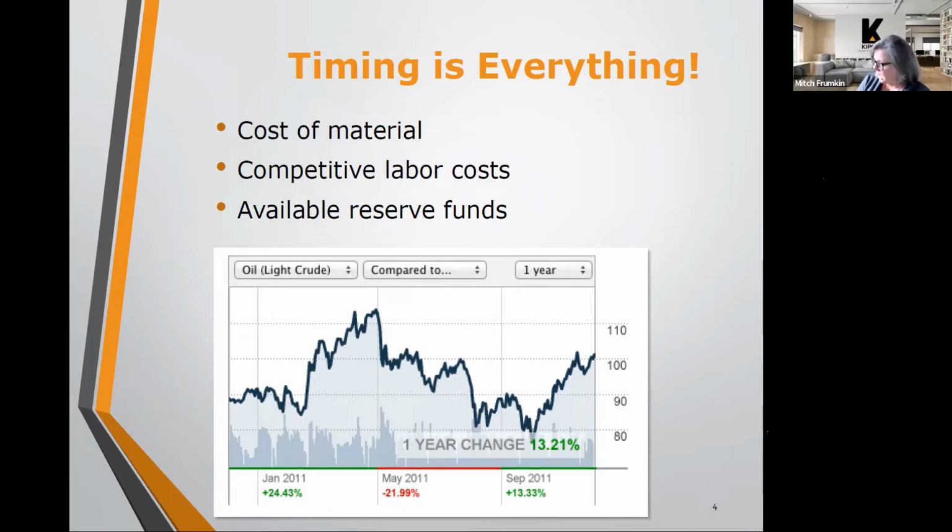Also, in timing of pavement projects, spring is ideal for doing pavement for several reasons. Number one is the temperature. Number two, you're not racing against the closing of the mills. So planning for a pavement project around this time is great, because you have time to put together the specs, gather your bids, select your contractor, and get on the schedule for the spring.